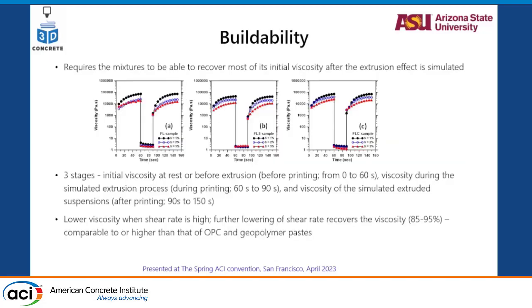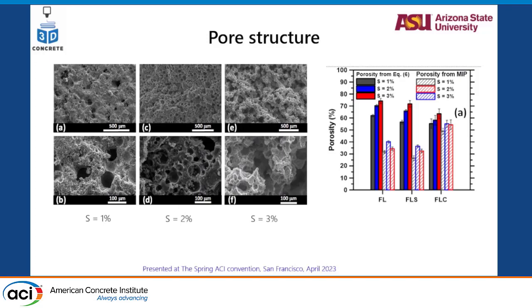If you want to look at buildability, here is viscosity recovery. That was the initial viscosity. You sheared it enough through the mixer to show what it goes through in the mixer. Later you are recovering most of your viscosity, which means I'm not breaking down the mix enough for it to be not buildable. Something very interesting to look at. And here is a microstructure of 3 different foams. You can see some very nice jammed foam structure with a very rigid skeleton in between.